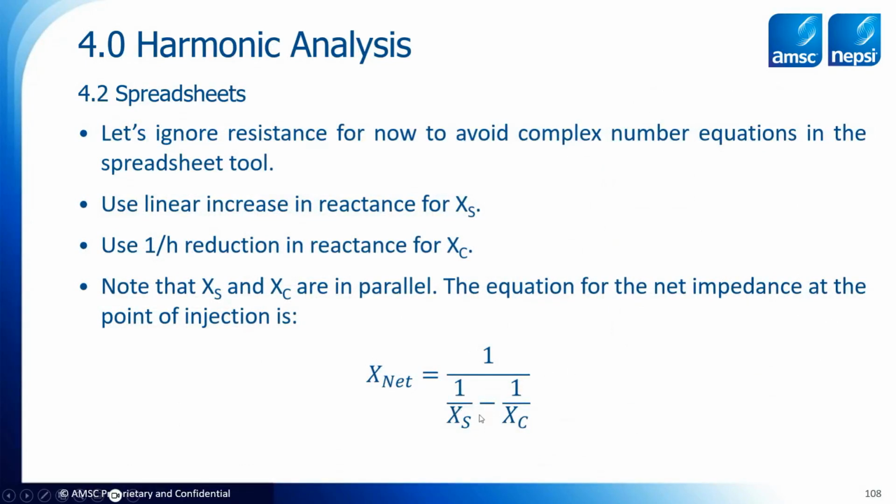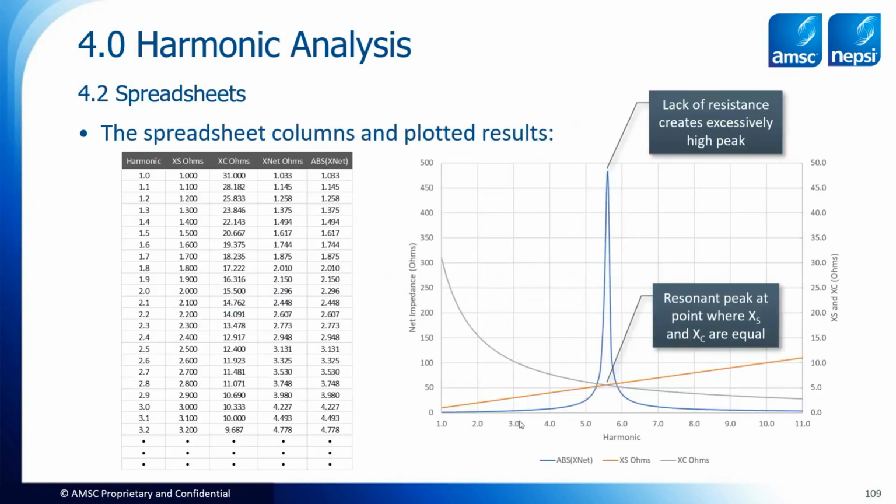And what happens is when these two values are equal, since they subtract from each other and because they're in the denominator, this will go to 0. 1 over 0 is an extremely high number. It's infinity. Well, it doesn't quite, in reality, there's some resistance in here. So it never goes to 1 over 0. But if these are ever exactly equal, you'll have a 0 divided. Fortunately, the way I did stepping, I never hit that exact point where they were equal. But you can do that numerically. You can get to just the right values and make this go undefined, at this resonant point.